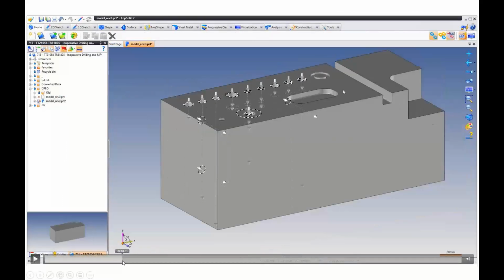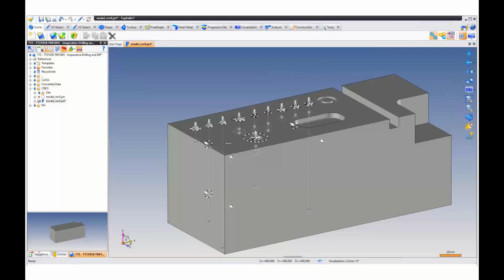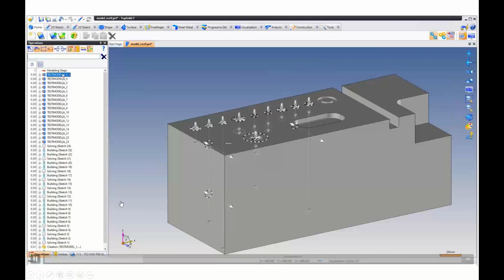So on the import, let this rotate, and I'm going to pause it for a second. So when we pause it, what do we see? This is an imported model, and you see manufacturing features. That's these little arrows here, okay, and these little wireframes. So they're just simplified representations of what these drillings actually are as read in from this CATIA file. If you look, and I can't zoom since it's a video, but it's converted that to a tapped hole because that's what the PMI was for this, okay? So let's just keep going here.